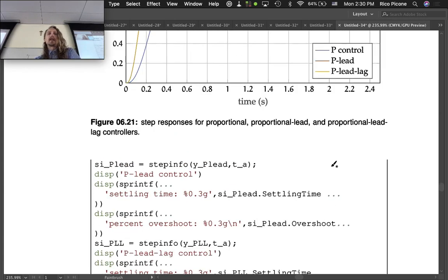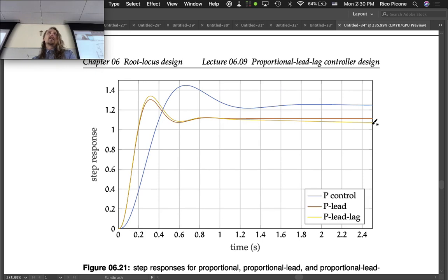What we run into though is a little bit of a quandary, because we can speed up this lag compensation. We can speed up this steady state error reduction by a couple different means: moving the poles and zeros in our compensators, increasing the gain, etc. There are ways to do it. But when I was playing with it, I didn't do a very extensive search, I noticed that we were really trading off going over our percent overshoot. As you adjust it, the percent overshoot kept increasing from here. So really, speeding up our steady state compensation is hard to do in this problem. So we're pretty limited there. So we're probably stuck with a slow steady state compensation, or we have to break our percent overshoot spec requirement. So we have this balance there, and you can explore it and trade off if you like.